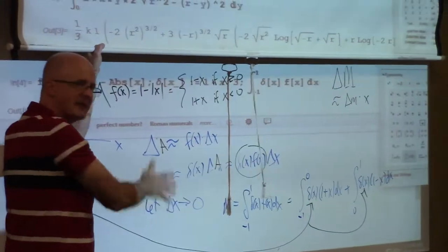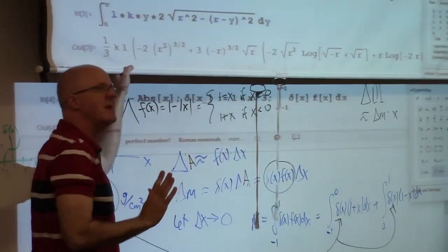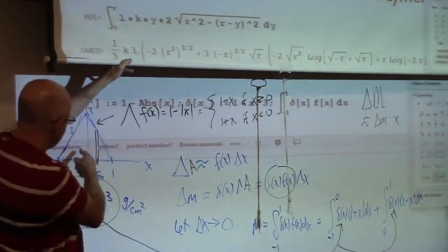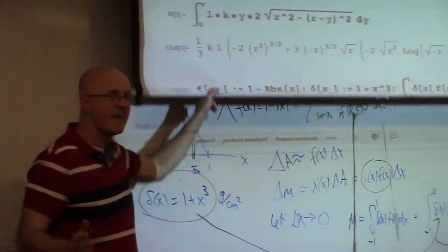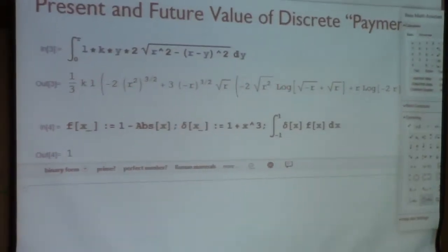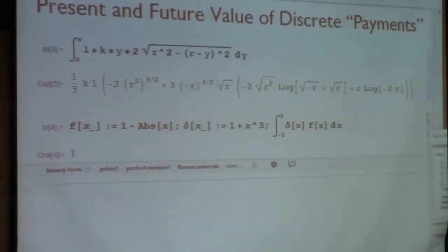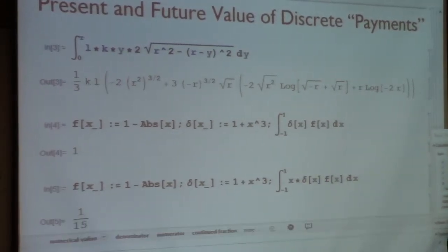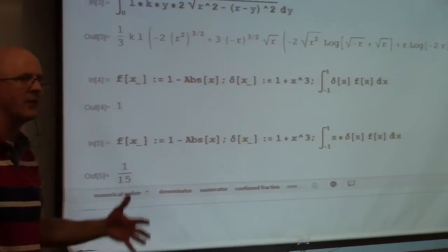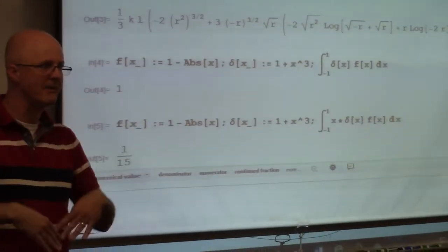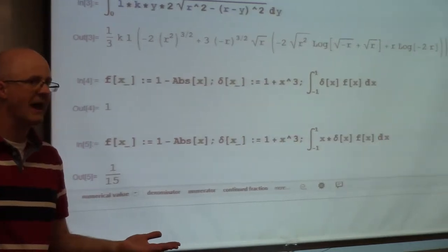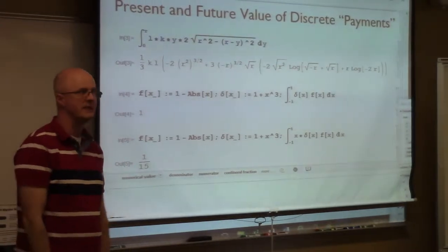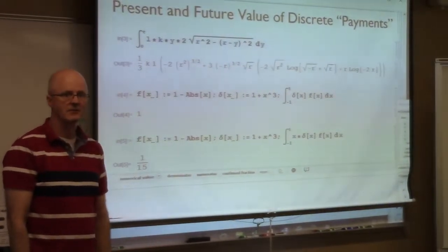Okay, everything else is the same, you just add an extra factor of x. That's that. Really, it's not a distance, it's a position. When you're to the right of the y-axis, that position is positive. When you're to the left of the y-axis, the position is negative. But the integral should be positive, I think. Add an extra factor of x in here. You do get a positive number. Then the ratio, capital M divided by little m, the moment divided by the mass, is the answer. The center of mass. In this case, 1/15 divided by 1 is 1/15. That's the x-coordinate of the center of mass.